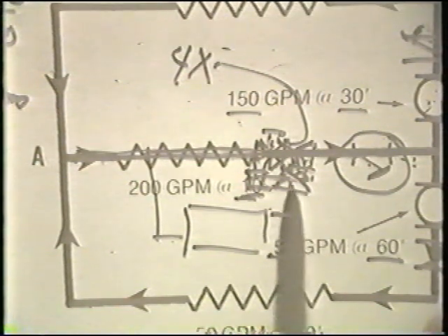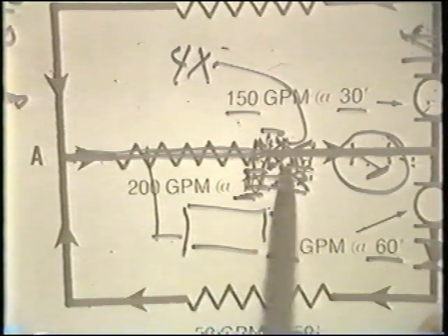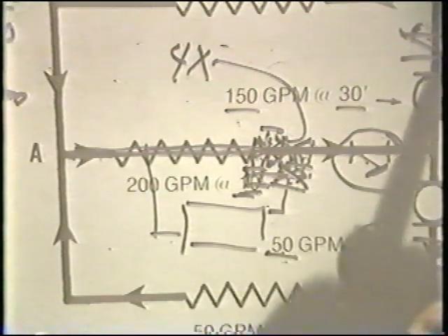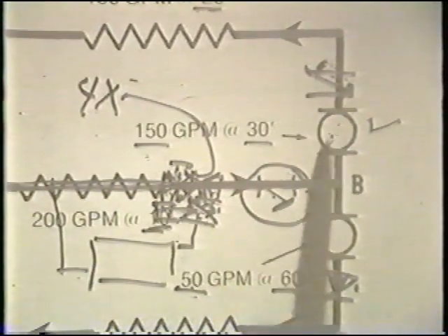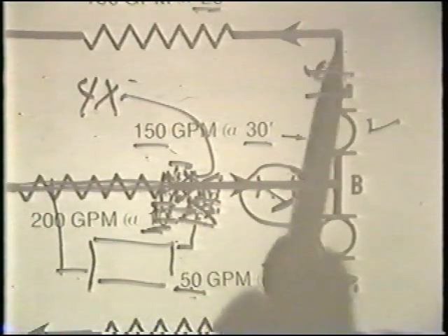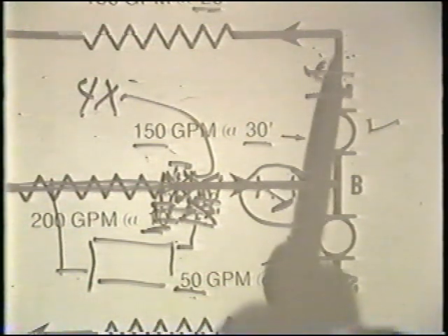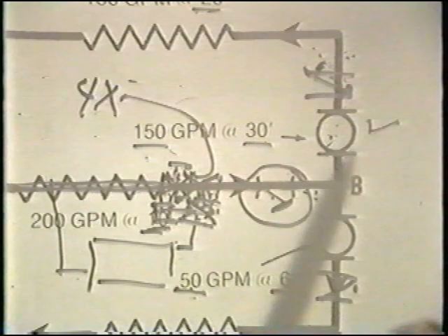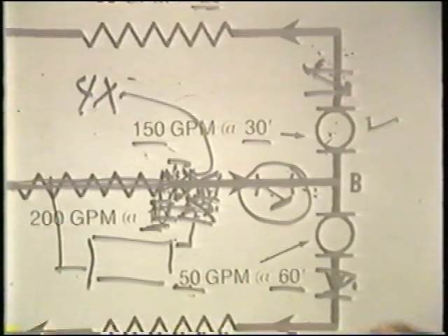So we can run into a condition then with butterflies where if the valves close off or go to a 50-50 position, we can again establish a very high back pressuring against the low head loss circuit, which will cause a decrease of flow rate for one thing, and under certain particular circumstances will close that check valve so as to potentially allow a freeze up in the piping circuit.